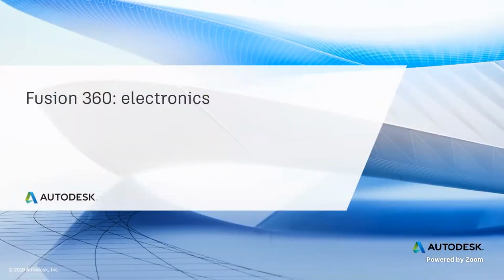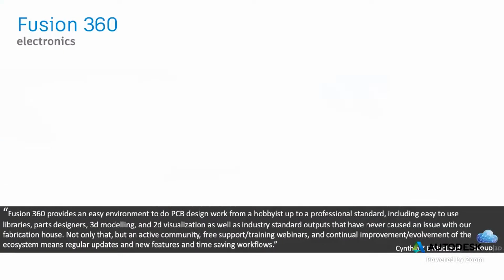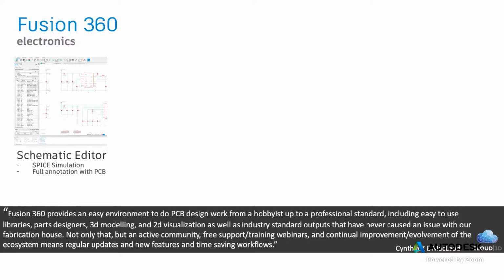Now, let's talk a little bit about the Fusion 360 electronics design capabilities. First of all, we have what's called a schematic editor. Our schematic editor does include a SPICE simulation capability, and the nice thing is that it's 100% annotation between the board layout. In other words, modifications done to the schematic actually affect the board in real time.